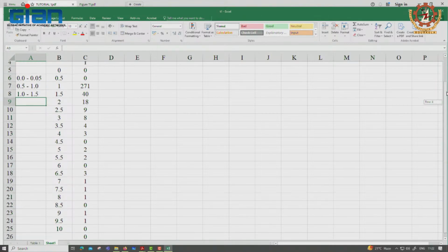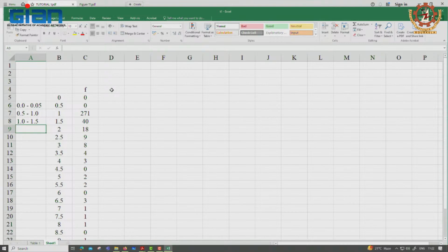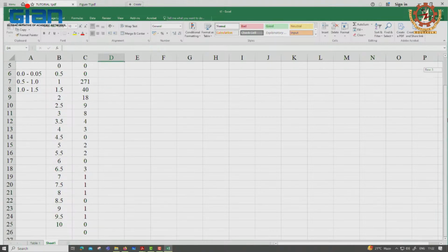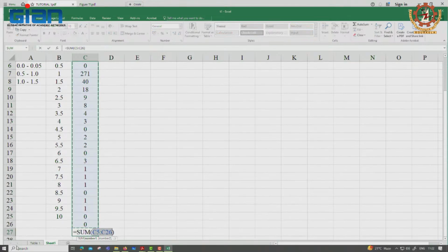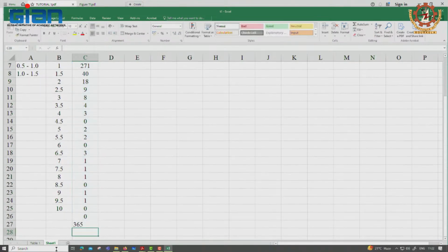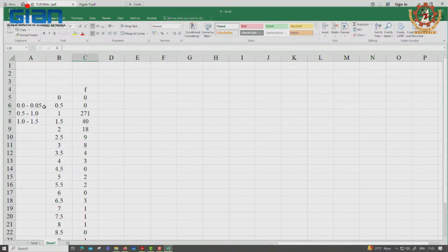So, now we can convert this to a flow duration curve by the technique I told you earlier, right. So, we can get the probability. Altogether there are 365 data points. So, the probability of each day's flow is really the frequency divided by 365.